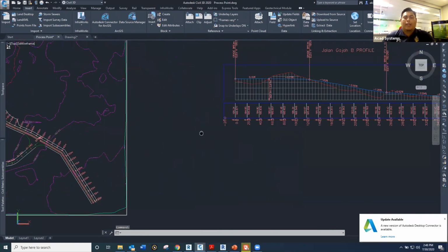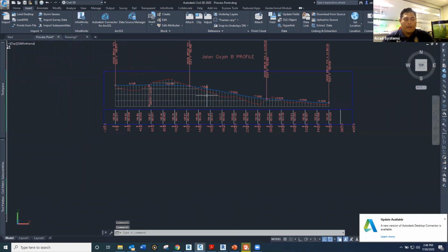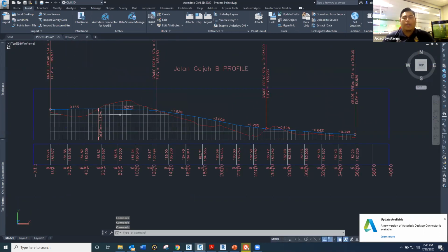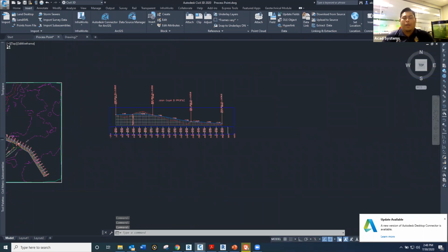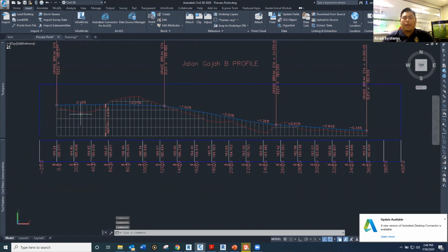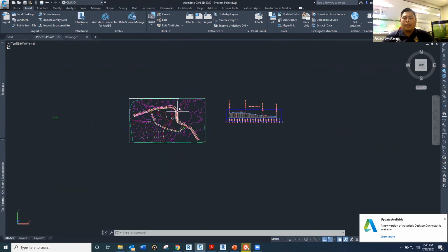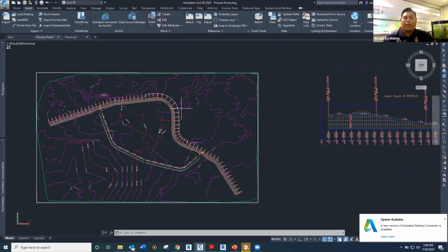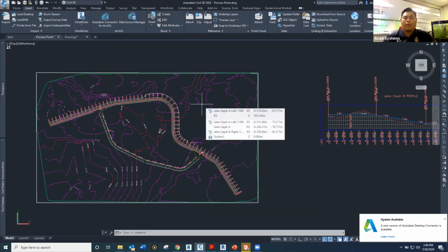And this is the profile that I created from the land. For the alignment that I created here, we will see there are some areas that need to be cut and filled. So for road designers, for any kind of infra workers and modelers, if you are going to model this up in Civil 3D, it's still workable. So I'm here to prove to you that when you have the cloud points ready from the surveyor, you should know, first, the right format that is workable for your workflow.